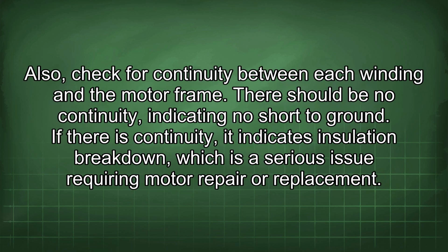Also, check for continuity between each winding and the motor frame. There should be no continuity, indicating no short to ground. If there is continuity, it indicates insulation breakdown, which is a serious issue requiring motor repair or replacement.